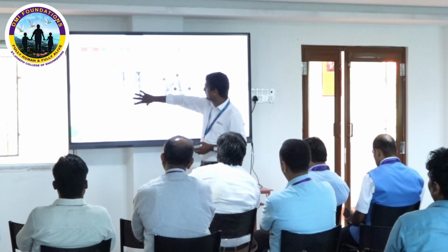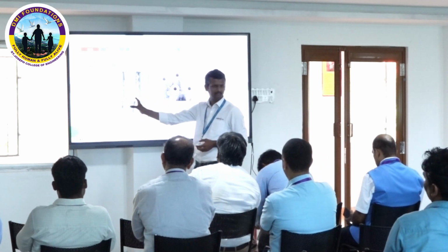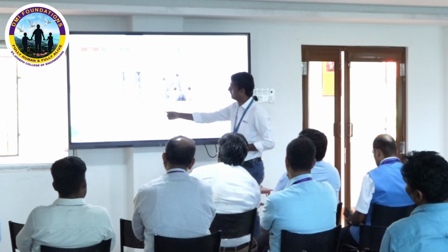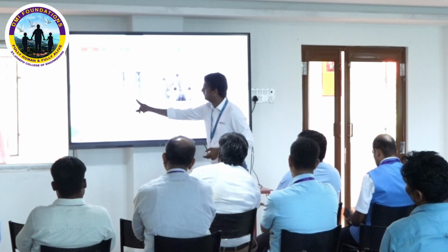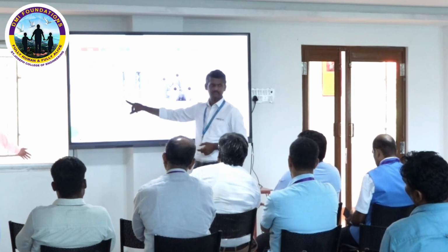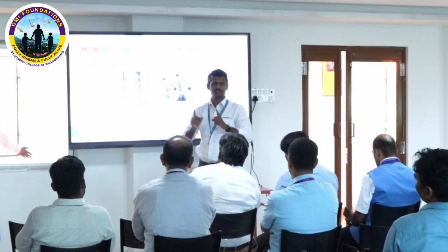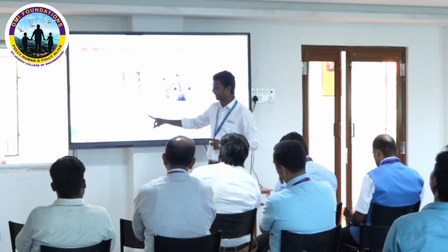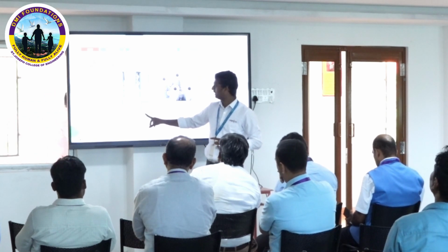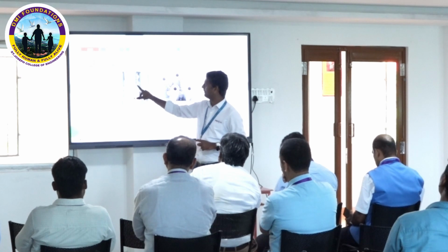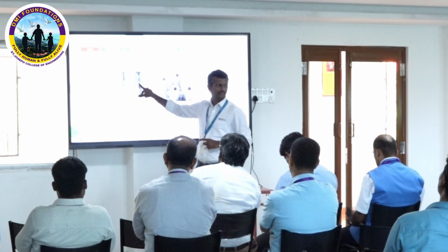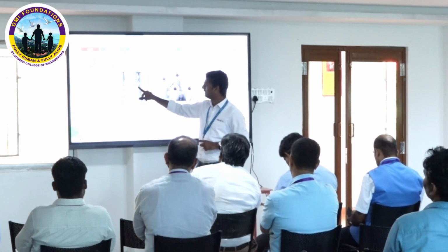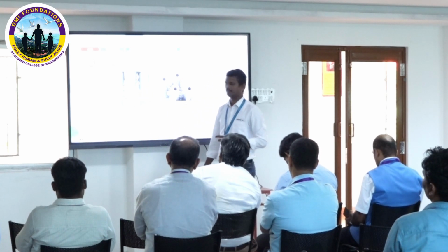So what they have done is this has been printed in an inverted way. Okay, not in this manner, in the inverted way it is printed. So in that case, these places you can see, they are designed in such a way that no support structure is required. And again these places, this curve is created in such a way that there is no support required. And the connectivity between these places is created as a lattice. So supports are not required, it is a self-supporting structure.